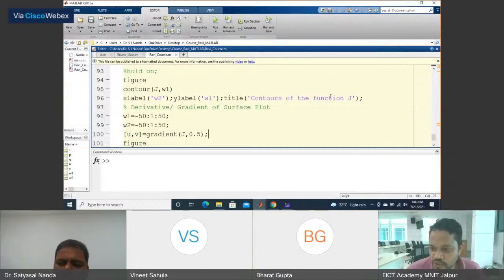There are some more questions. MATLAB's default saving option is .fig files. Instead of them, they can save it as an .eps file. But there's a small catch. If you save it as EPS, you cannot edit it again in MATLAB. So you need to keep a copy of your original .fig also. Otherwise, you'll have to generate it again from the MATLAB code.